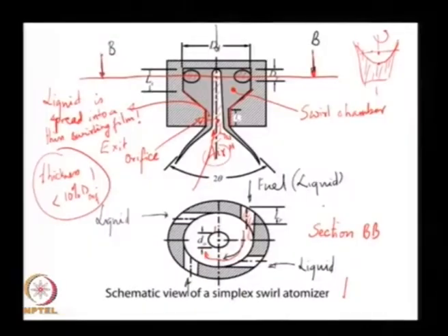See how this is fundamentally different from the diesel case. The diesel atomizer, the diesel injector was a situation where the orifice was completely flooded with liquid. The only interfacial area there was the surface area of that cylinder exiting the injector. Here the interface is now twofold. There is an interface on the inside here and an interface on the outside. So, I get twice the benefit for the same orifice size, and because I have spread it out into a